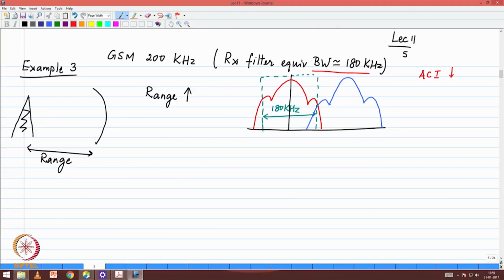What happens to the noise? What noise is going into the receiver? Because you have your signal and you have actually filtered your noise, so you get colored noise. Coloration of the noise, or the channel basically, is introducing memory into the system, which means that you would have to have an equalizer. You have gained in terms of the adjacent channel interference, but the price that you have paid is that your receiver will now become more complex.